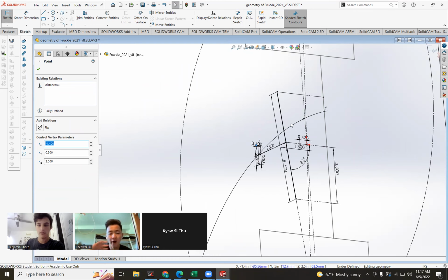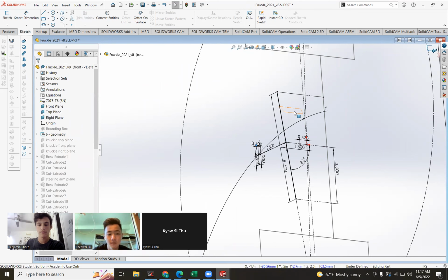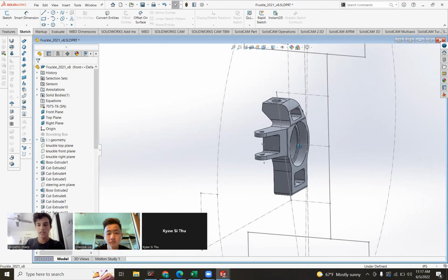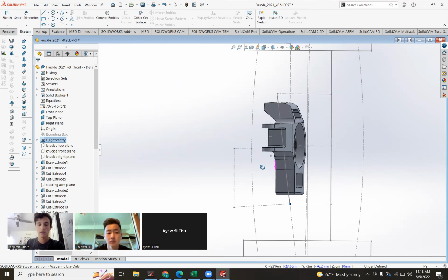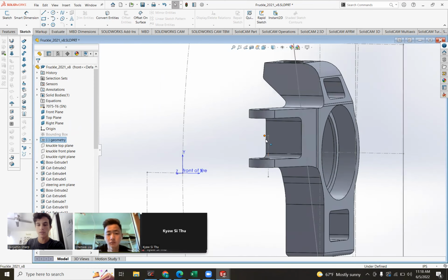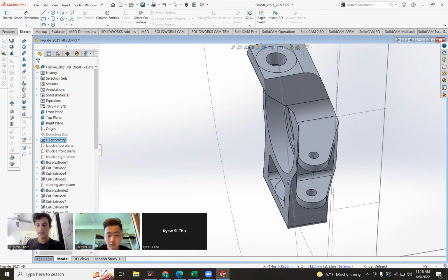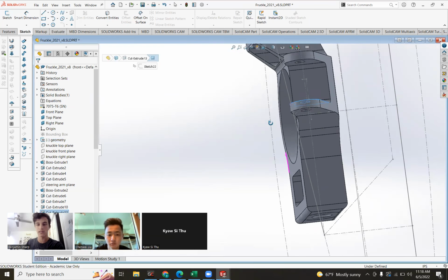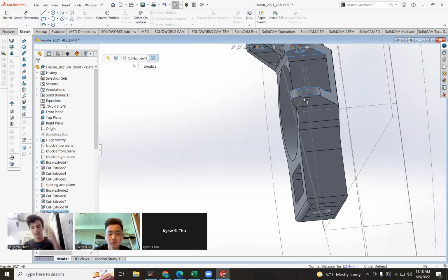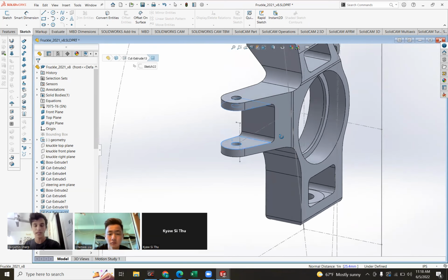But if I just go back and forth between this sketch and the knuckle, you can see a couple things that I was talking about. So how the spherical bearing sits on top and on the bottom. How this point at the end of the tie rod is in the middle of this mounting hole. Although this distance, actually pretty importantly, needs to be smaller next year because I made it too big. I'm sure you guys remember that.